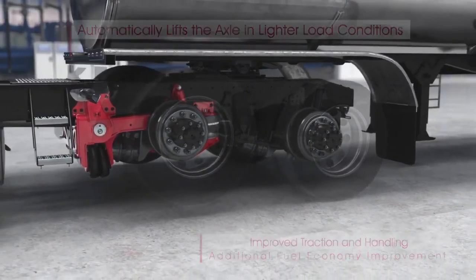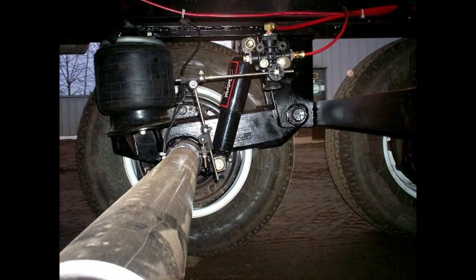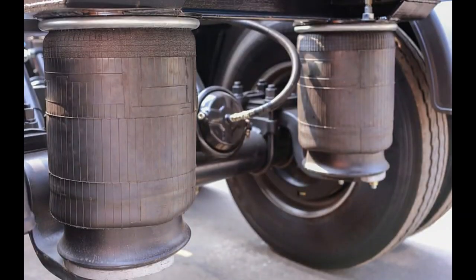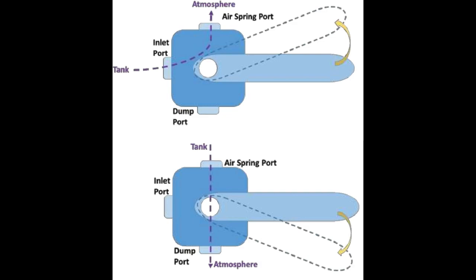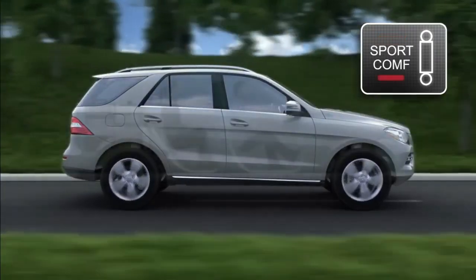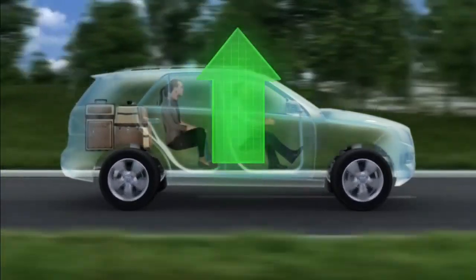Third is supply line. Supply lines play a vital role in transporting the compressed air to the airbags within the suspension system. These lines closely resemble standard high-pressure airline tubing and are typically routed alongside the vehicle's frame. Supply lines are typically constructed from rubber or polyurethane materials. However, in some cases, custom steel lines can be used as an alternative. These steel lines not only provide a more polished appearance but also offer increased durability and sturdiness.